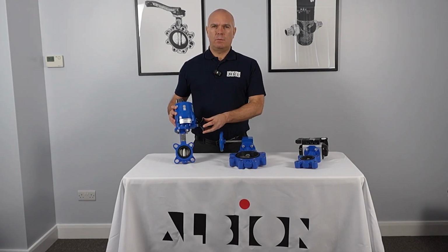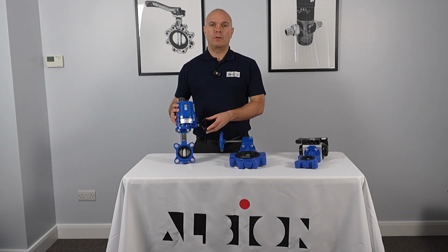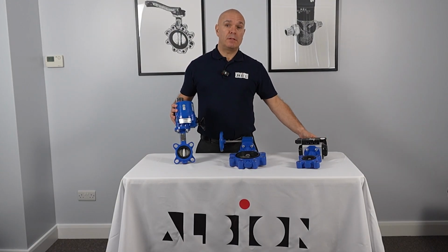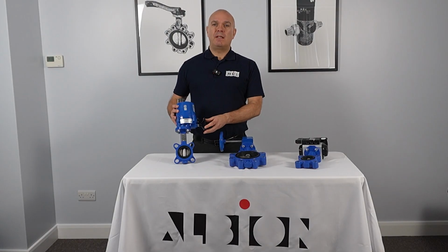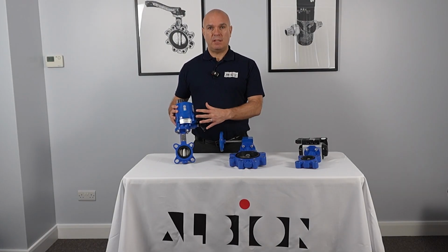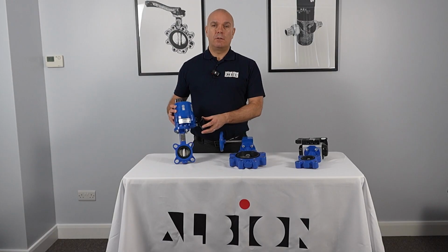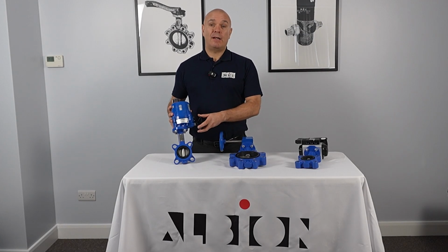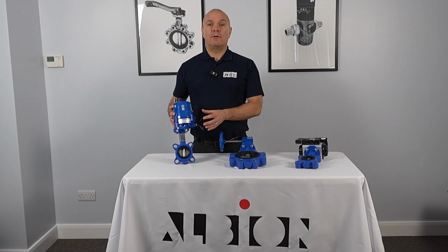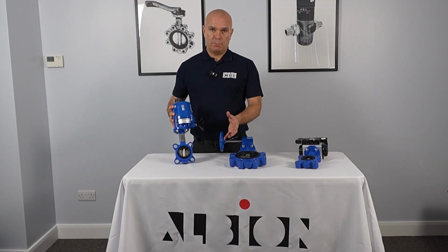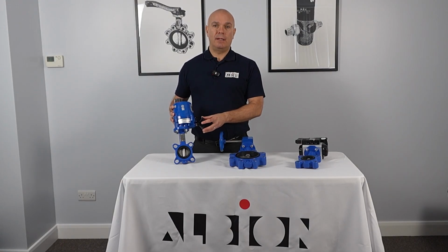These types of actuators work just like the pneumatic actuators when used in conjunction with the NAMUR and the switchbox accessories, and allow feedback signals to be both sent and received. These electric actuators can also link into a building management system. One of the great things about Albion's range of both pneumatic and electric actuators is that they can operate in either a fully open position, a fully closed position, or even a proportionally controlled configuration, which is an ideal solution to regulate and control the flow within a pipeline system.